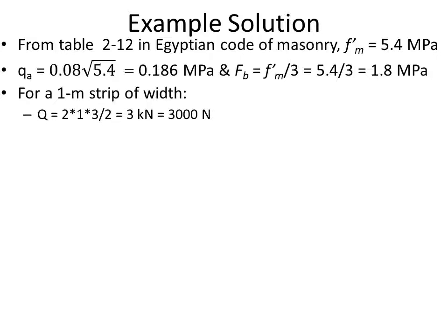And by the way, we forgot to mention that this wall is considered to be simply supported because you're having a ground beam at the base, and at the top of the wall you have a lintel or another RCB. The distance between them is 3 meters.